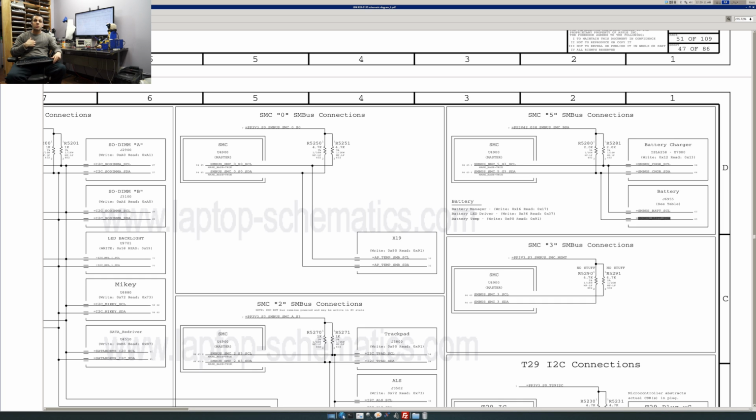Do I know what the pulses mean? No clue. Do I know what any of those pulses mean, what the code is? No. And that is for people who are much smarter than me, who had a much better college experience than I did. But all you need to do is see that there's pulses there, compare to another board that works, get an idea if it's close, and you'll know.